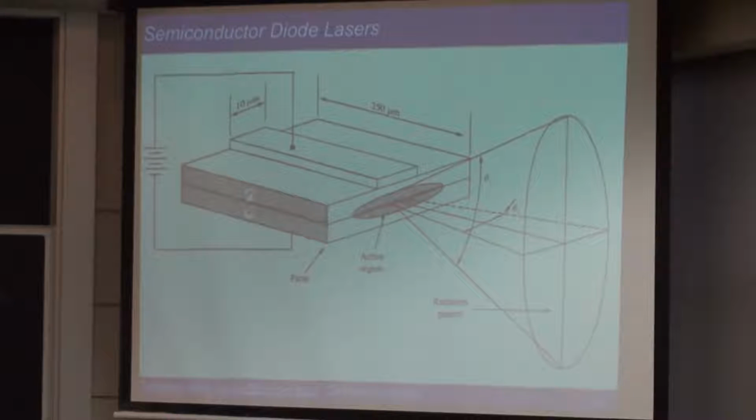On the other hand, if you're looking at larger gas lasers or solid state lasers, you're typically talking about kilovolts or hundreds of volts, because you want to inject electrons and make them collide with things, and if you look at excimer or whatever, you're applying very high voltages there. Here you're applying very small volts and injecting reasonable amounts of current, which is why it makes it easy to make handheld lasers and mobile ones as well. And the efficiency of this is also extremely high, and you can get very high power output.